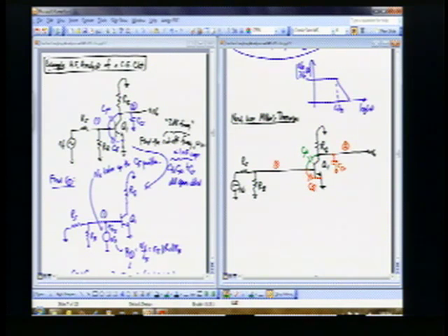So what I want to do is get that capacitor out of the feedback path. The reason why it gives us problems is because it's in the feedback path. Right? And so like I said, anytime you have something in the feedback path, it's going to force you to do more work. You have to do small signal analysis, that sort of thing. Now, we did the small signal analysis. Well, you did it in some previous course. And we're just memorizing the equation. Or you can say, I don't want to memorize that equation. I know C mu is there, but let me not treat it as C mu. Let's get rid of it.